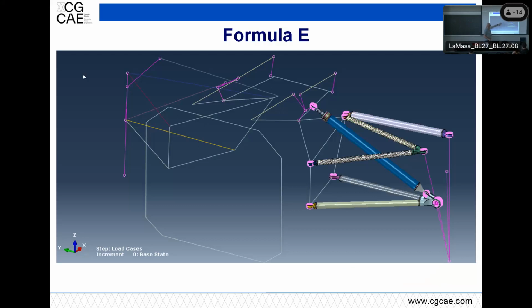So we agreed on where we can reduce their structure to the points, the connection points, and the constraint points to the monocoque and to the suspension element. I was in charge to size and check the suspension element. This is a push rod. It's the one which is, during the movement, activating a part here which is called rocker, which rotates, and it's connected to a damper, spring, anti-roll bar system, and whatever you can imagine to place in that car.